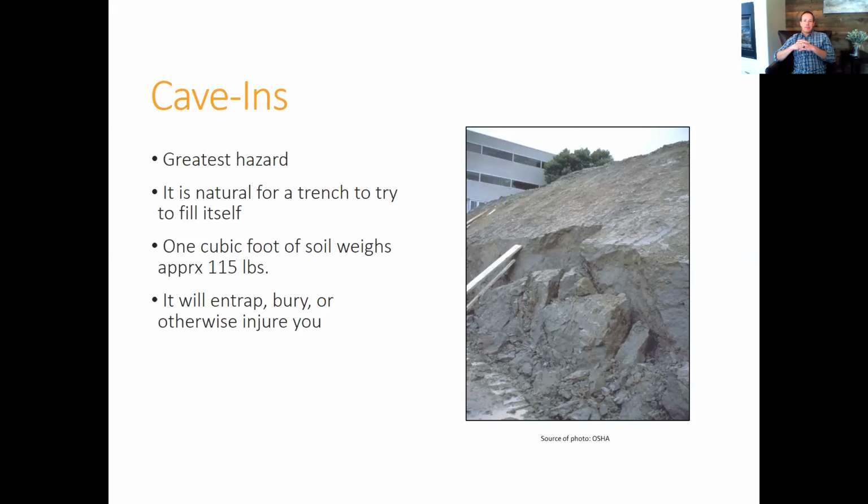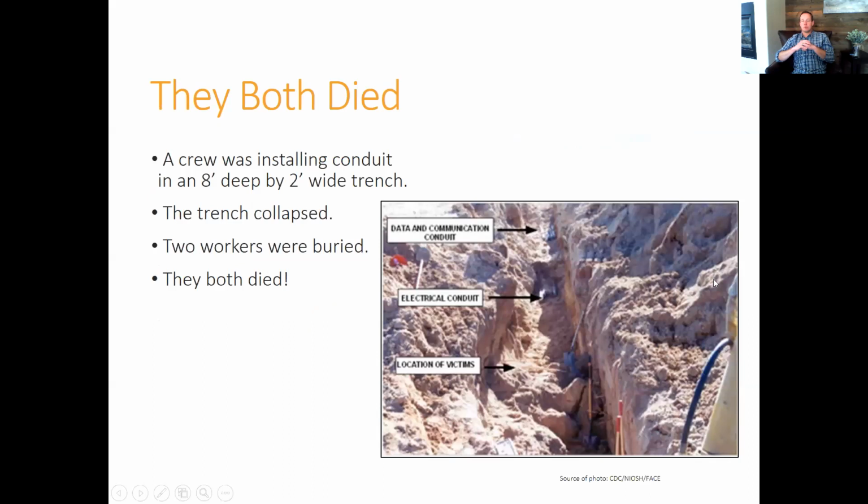And now we know that the greatest hazard of our excavations is a cave-in, okay? It's a cave-in, somebody being buried. That is the greatest hazard that we have to deal with. And so we've determined the different types of soils, and we need to be able to deal with those.